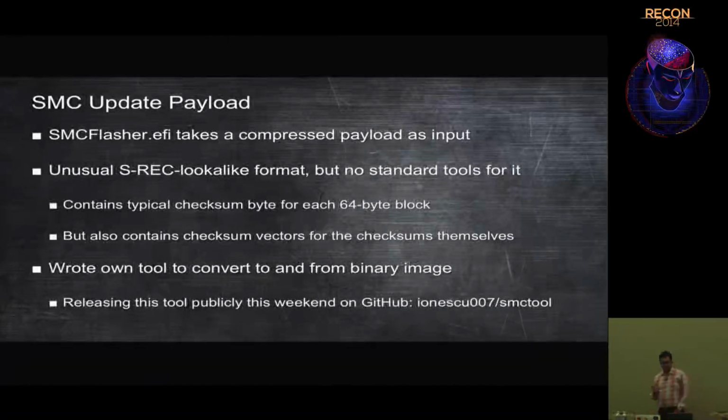Well, it's a bizarre compressed payload, which is ASCII, so it looks kind of like Motorola hex or SREC. It has basically a checksum for each ASCII string, but then it contains checksums of checksums and checksums of checksums of checksums. So it's a little bit of an interesting format, but I wrote my own tool to basically dump this kind of file format into a binary file, and also to go from a binary file into this format.